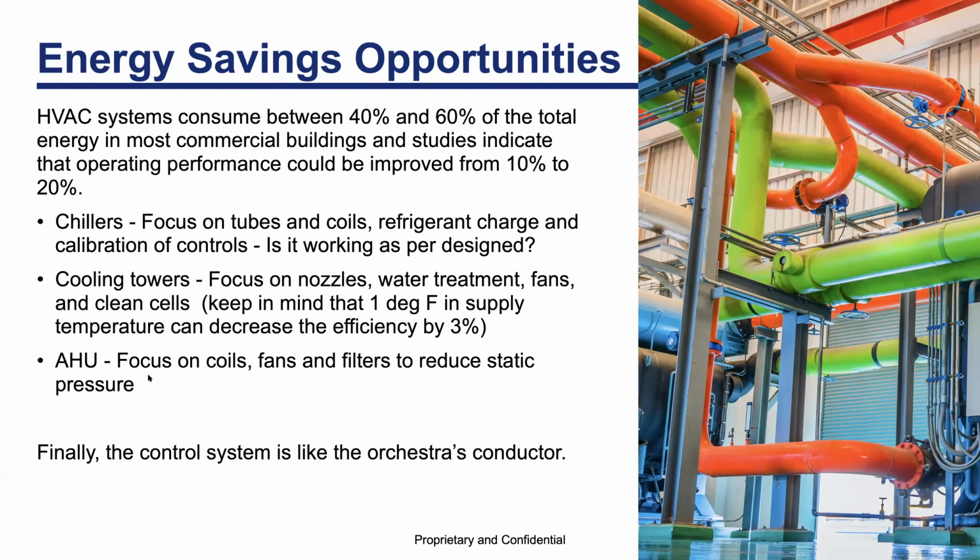As far as air handling units, again, know the temperature differential that the coils were selected for. We all know that new rules or guidelines are in place concerning indoor air quality, IAQ, in which one area to consider for retrofit is air filters, and basically it is to consider increasing the MERV rating to 13 or even 14. We all know that MERV 8 is the basic one, especially for residential, but for some commercial applications, I've seen a lot of MERV 8.